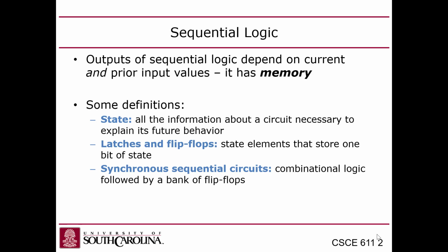Okay, so I mentioned, I think in the second lecture, that there's combinational logic where you have a logic circuit that calculates an output as a function of the inputs at any given time. Then in the last lecture we said, well, there's actually a propagation delay. So whenever you change any of the inputs of a combinational logic circuit, it updates the output as soon as it can once the signals propagate their way through the gates. So there's a propagation delay.